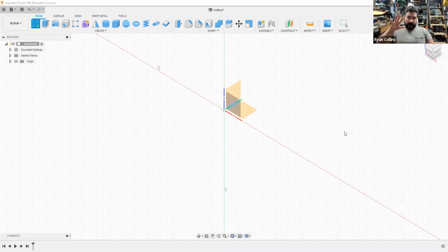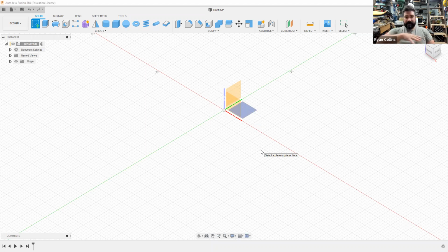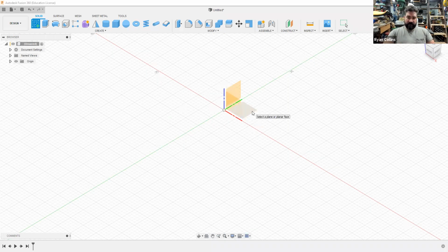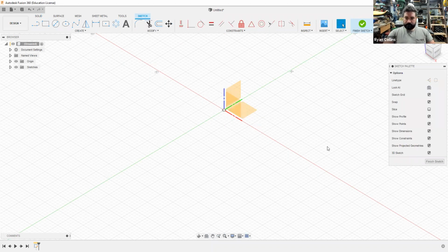So when you're working on the standard sketch set, usually it's going to default to the XY plane. Looking straight down, that's basically looking at a table in front of you. If you're working straight in front of you, that would be the XZ plane. And you can select those by mousing over these different flat planar spots. I mouse over the XY plane, which is between the green and red. There we go. So I'll be working there. Now that I've started a sketch, you can see that the toolbar at the top has completely changed. Now you are seeing all of your sketch line property tools.